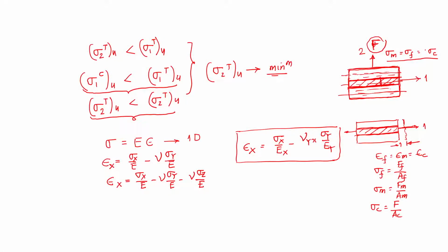A unidirectional glass epoxy lamina is loaded in a UTM along direction 1 and the corresponding increasing stress values, the strains along 1 and 2 are recorded. Find the longitudinal Young's modulus, the major Poisson's ratio, and the lamina is now subjected to biaxial normal stress, the longitudinal strain. So I'll just solve it. Just look at this. So it's given that these 3 values are given.